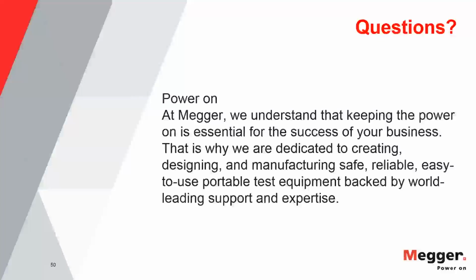What is the minimum rated voltage where PD is a useful test? Any rated voltage. The limitation I would say is that you have to make sure that the cable has a shield on it. So your very low voltage, your 480 volt cables, they're not mechanically constructed in a way that would be conducive to PD testing. But as long as the cable has a shield on it, so your 5 kV rated cables and above, you should be able to do some PD testing on it.